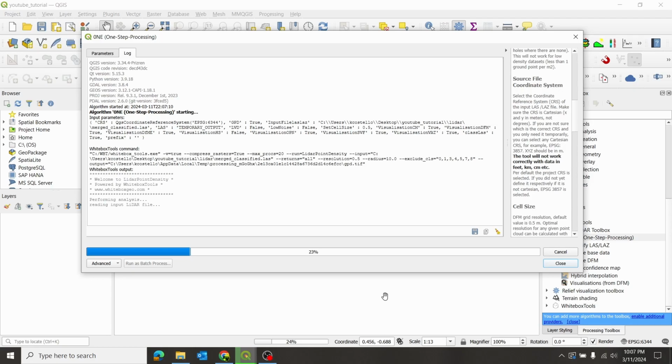One of the other things I like to do in Cloud Compare is view my point cloud. I'll zoom way in, and you'll notice you have a small scale bar at the bottom right-hand corner of your screen. I'll zoom way in until that scale bar is 1, which is 1 meter, and compare it to the points that are represented on the ground.